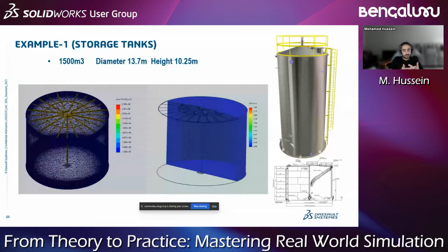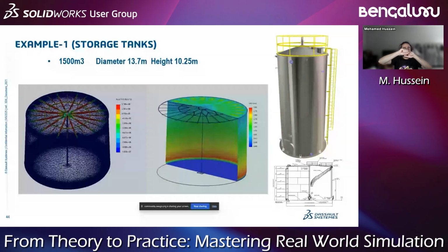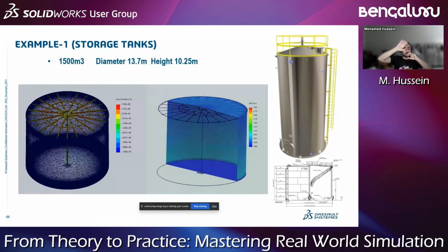We have another kind of contact, for example, which is called shrink fit. What is shrink fit is whenever you are having something that goes inside another one, sometimes we are doing some heating just to enlarge a certain area, and after it enters, it squeezes again due to the temperature difference. This is the shrink fit.